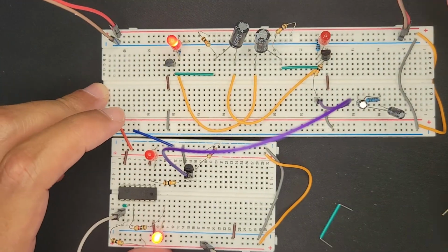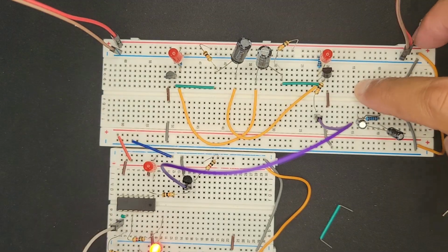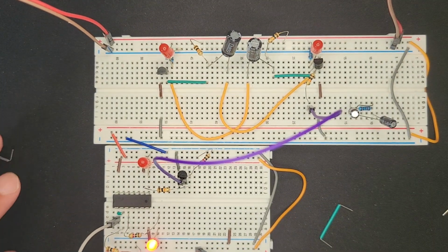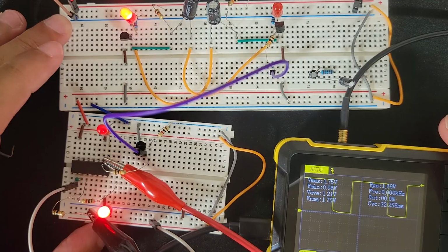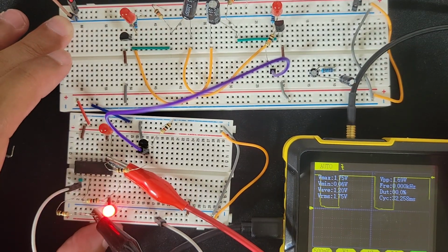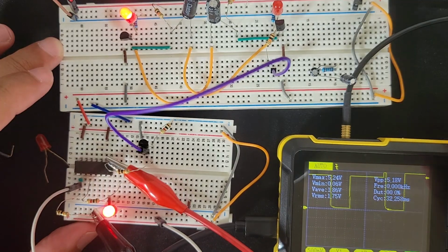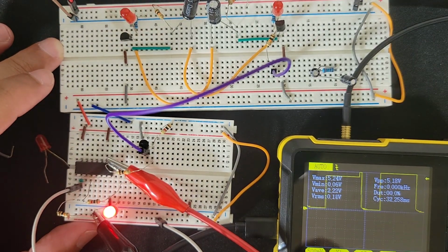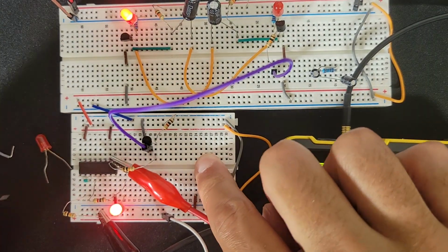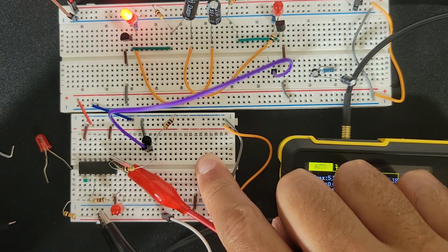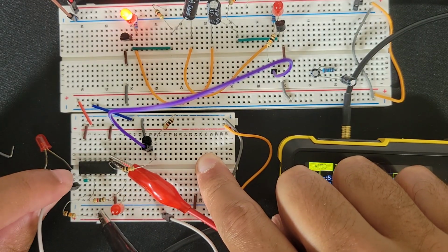So maybe the signal also wasn't strong enough, because now we should be getting more voltage. I guess I should double check that. So let's plug this in again and see. Still getting only 1.75 volts there. How is that possible? Maybe if I plug out the LED. Now it's up to 5. Oh yeah, that made a big difference. So was the LED killing me the whole time? Let's see if it's working now. Yeah, I think it's working now.